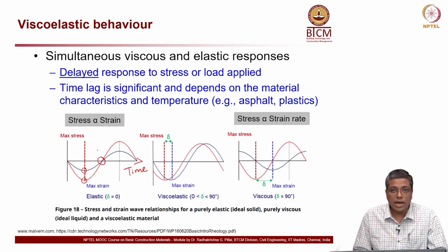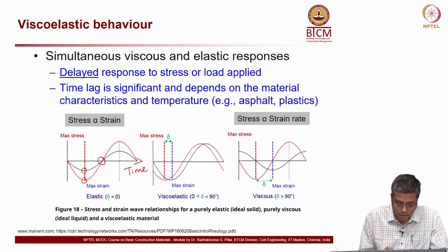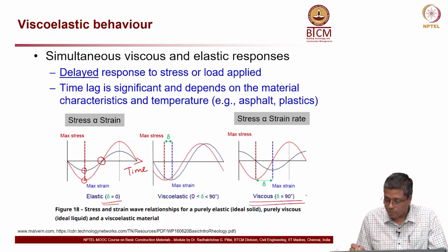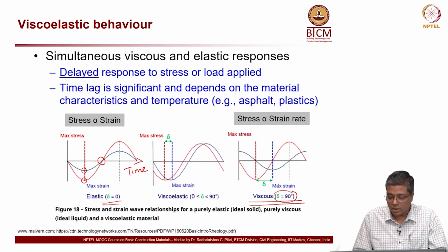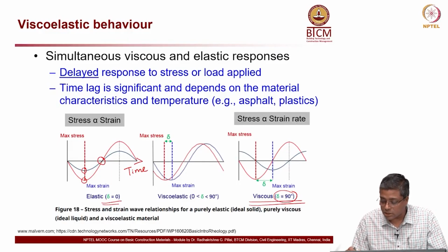So, the time lag is insignificant or almost 0 in case of elastic behavior, or there is no phase difference. If you are looking at the viscous behavior, which is on the right side, there is a phase difference of about 90 degrees, and what that means is there is significant time lag, and also the stress is proportional to the strain rate and not just the strain.